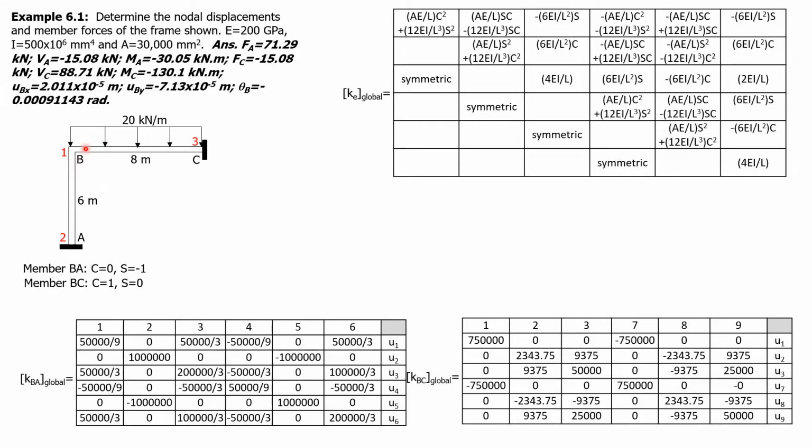So we only want the nodal forces at node 1 represented by U1, U2, U3. These are the unknowns. And at 2, everything is 0: horizontal, vertical, and rotation, because these are fixed, as well as at 3. So we can reduce the global matrix into 3 by 3. We are only interested in 1, 2, 3. So 1, 1 is 50,000.